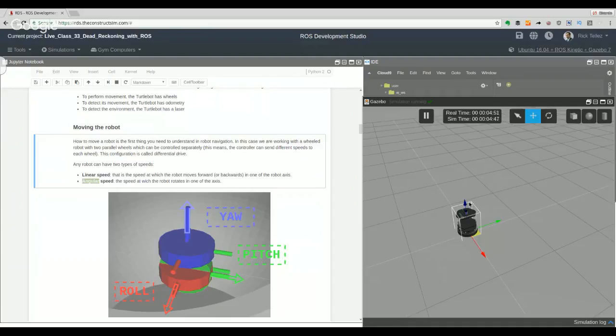So that's the Z axis. When you apply an angular speed to a differential drive, the robot will rotate on this axis. Let me show you how. If I click here, I can emulate as if I am applying a velocity. The robot will rotate in this sense. This is what happens to the robot when you apply an angular speed. Remember, we have linear speed and angular speed. Linear makes it move forward, angular makes it rotate.